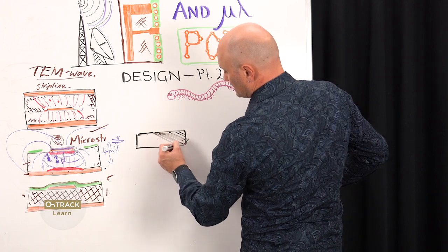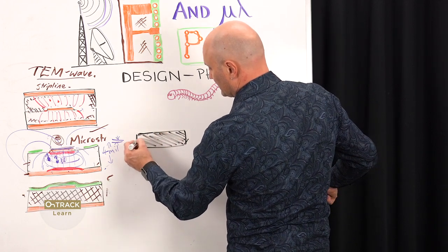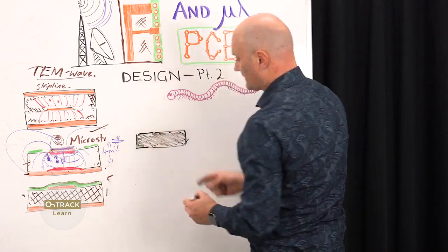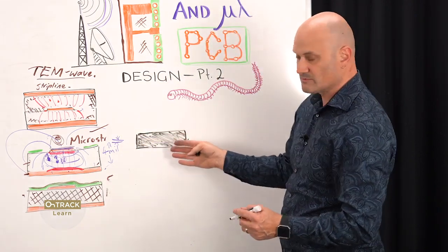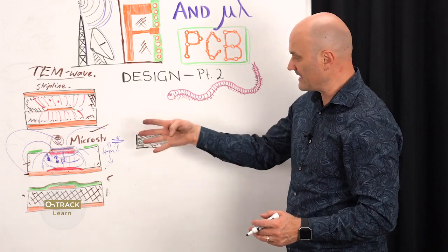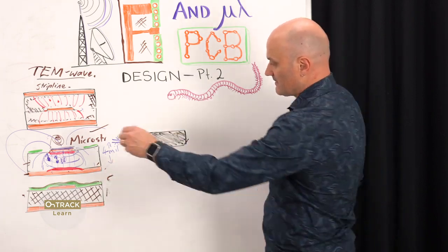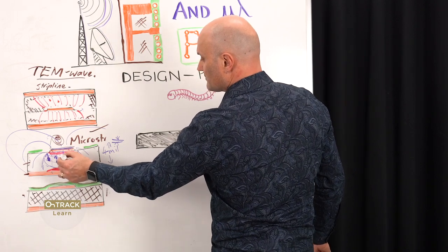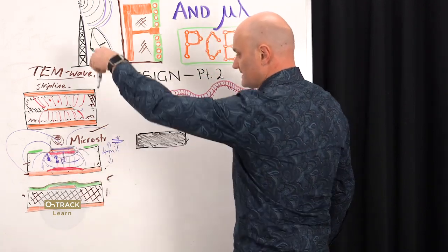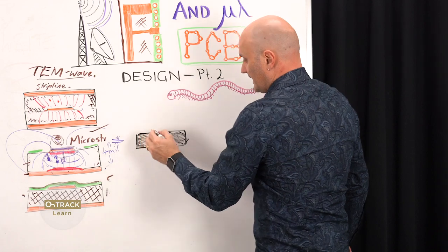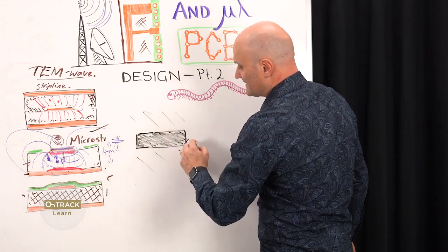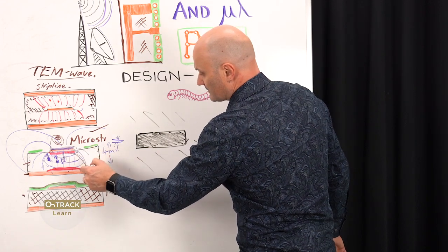And the textbooks will look like this. Now, I've actually seen YouTube videos where people getting into this for the first time didn't realize that that's not just your piece of copper, but there's actually a plane layer underneath it. If we're looking into the structure on the edge of the board here, in this case we're looking down from on top. And so we take for granted that there's a copper plane underneath that as your reference plane.